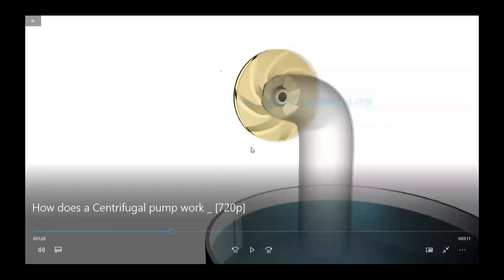So that's why sometimes we have to pour water into that centrifugal pump from the piping system so that we can have water here and enough negative pressure can be created. If there is no water here, then as the video said, that negative pressure would be negligible to serve the water.